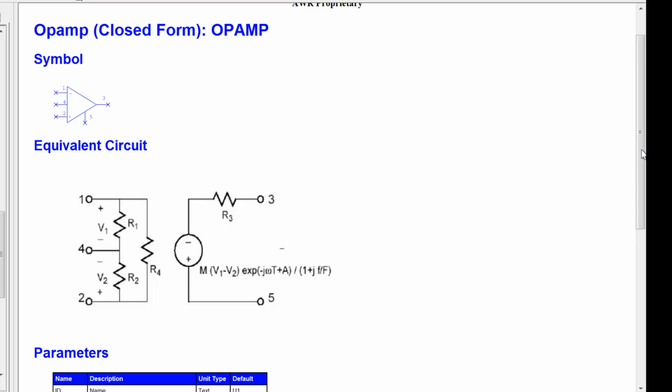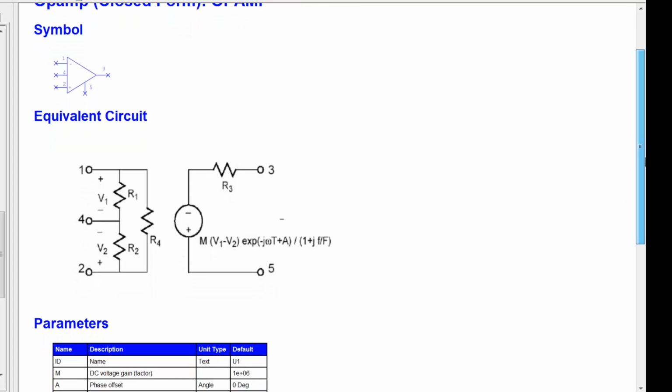Now, I don't want to go into great detail about these because I think it may be a little bit too much for you to take in at this stage. However, what we want to try and do is make this model as similar as possible to the one that we had in the lectures. So we want to get rid of this R1 here and this R2 here, and we want to completely ignore this pin 4. So we'll leave pin 4 unconnected, and we want to set R1 and R2 to values which mean that they won't matter at all. And because they are in shunt with the input, which is between pins 1 and 2, if we make them infinite, this means that effectively they would be like an open circuit. A shunt branch with infinite resistance effectively behaves like an open circuit.